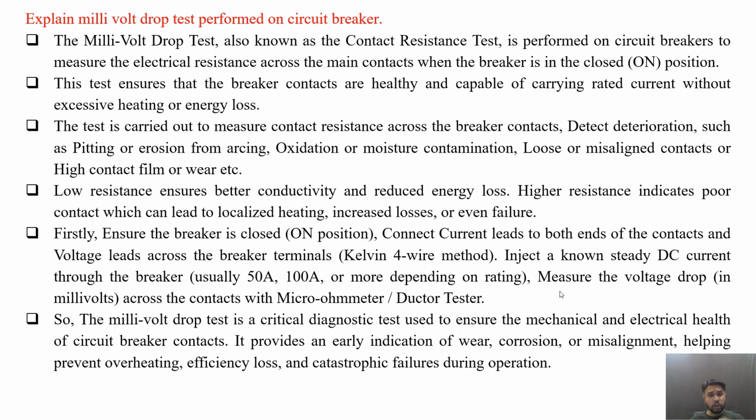So the millivolt drop test is a critical diagnostic test used to ensure the mechanical and electrical health of the circuit breaker contacts. It provides an early indication of wear, corrosion or misalignment, helping prevent overheating, efficiency loss and catastrophic failures during the operation. So this is all about millivolt drop test or contact resistance test performed on circuit breaker.